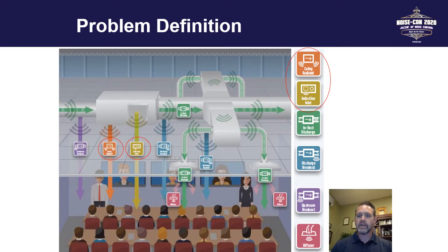You can have casing radiated noise. You can have induction inlet, sometimes referred to as return noise. You can have in-duct noise from the fan if it's a fan-powered type of unit, upstream or downstream of the unit. You could potentially have breakout noise, upstream or downstream of the unit. And you could certainly have some noise at the diffuser as well if the diffuser is not properly selected for the application and the type of the unit.